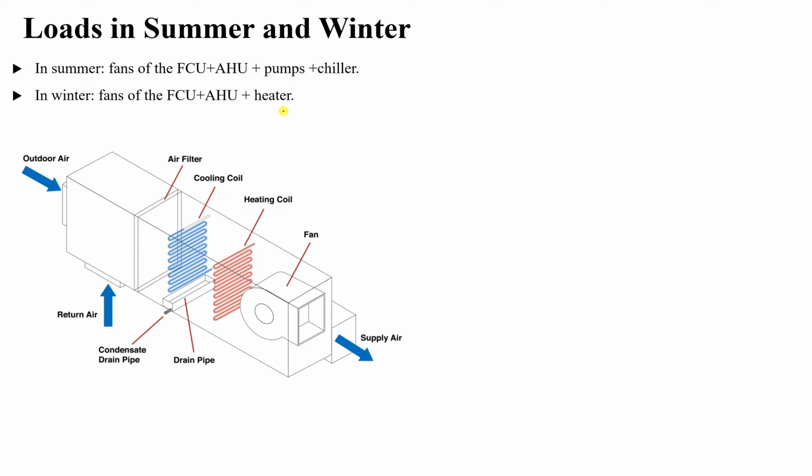Okay, great. So let's look at this. When we size our electrical transformer for our system, we design it based on the summer loads, and we size the sub distribution board on winter loads. This is a mistake, sub distribution board.